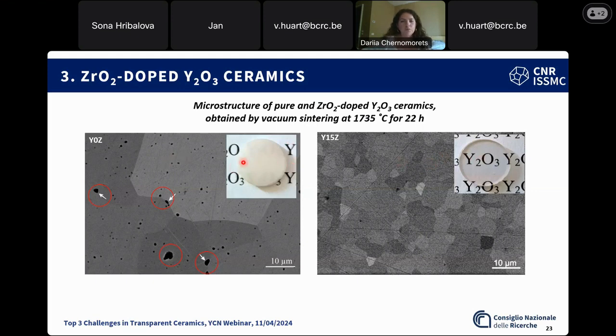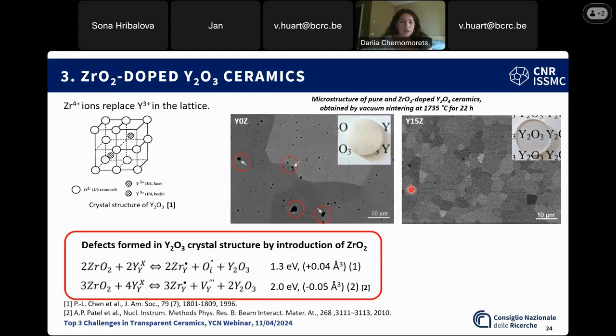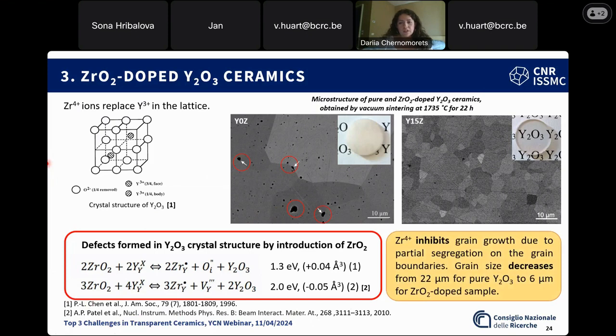There's another question regarding the light scattering, and the question is: do the clean grain boundaries scatter the light? Well, in principle, if they're clean, they shouldn't. By clean, we mean that there are no secondary phases, no phase or area that would have a different refractive index, because if that was the case, then I would expect scattering there. If the grain boundaries are clean, the answer should be no for light.